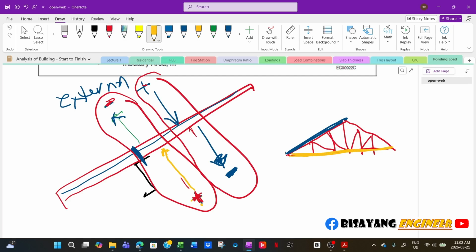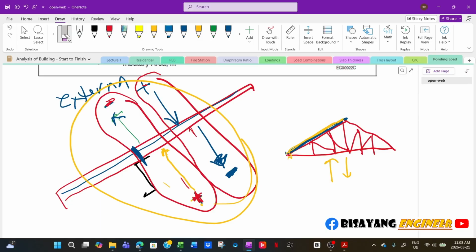So in this case, you don't do this addition and subtraction, because for your roof cladding it's different: any internal pressure will not be acting below the roofing, because you have a ceiling. But if you don't have a ceiling, that means your internal pressure will also be acting on the roof. So just make sure that you account for that.